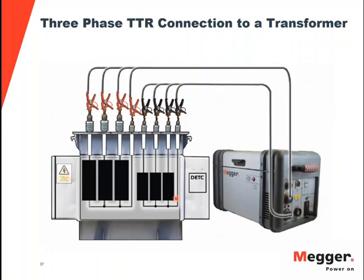But sometimes you may not have equal distribution of voltage between the taps. And then what would happen is that if you were to do the TTR test, you would fall outside of the 0.5% tolerance. And as long as it is consistent on A, B, and C phase, you should be okay. Or as long as it matches the commissioning results or factory results, you should be okay. But keep an eye on those things.